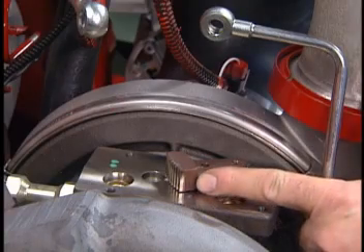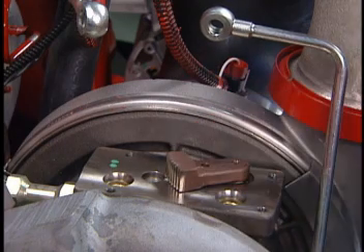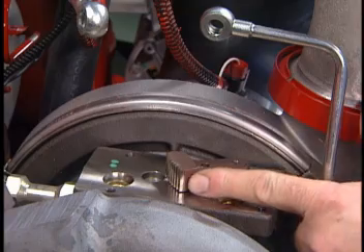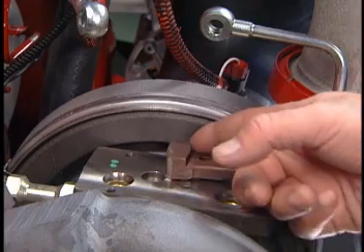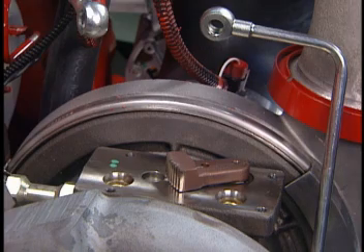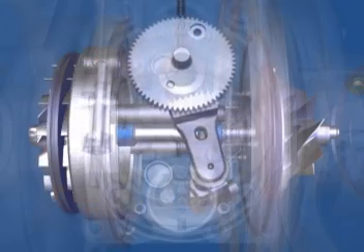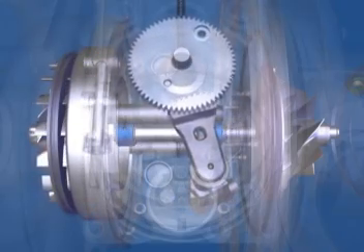Inspect the sector gear on the turbocharger for excessive wear, damaged teeth, or a broken shaft. Grasp the sector gear and move it through its operational range. The sector gear must move smoothly through the range of motion. Excessive force should not be required to move the sector gear. Within the turbocharger, there are solid end stops which limit sector gear travel in both directions.